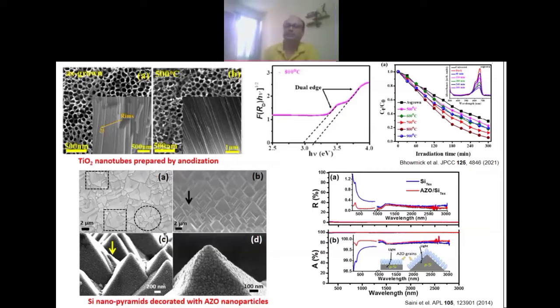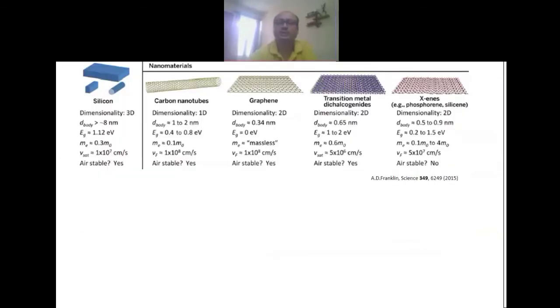But in the case of a semiconductor, since there is a band gap, you have free space here, but the electrons are up to the valence band maxima, so you have to populate the conduction band so that electrons can participate in the conduction mechanism. With temperature, you are supplying extra energy through kT. If kT is sufficient, electrons can populate the conduction band, and a number of electrons can reach the conduction band and participate in the conduction mechanism.